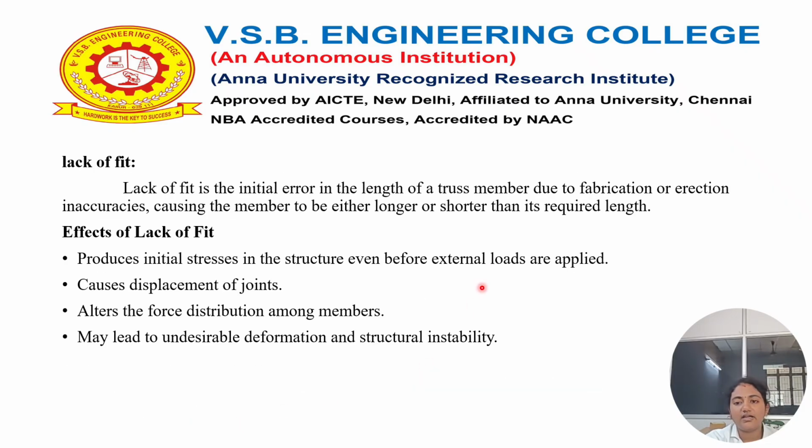And lack of fit. Lack of fit is the initial error due to fabrication and erection inaccuracy, which causes members to be longer or shorter than their required length. While erecting or fabricating, inaccuracies may occur, and in such cases lack of fit will be considered. It causes displacement of joints, the force distribution among the members will vary, and it may lead to structural instability.